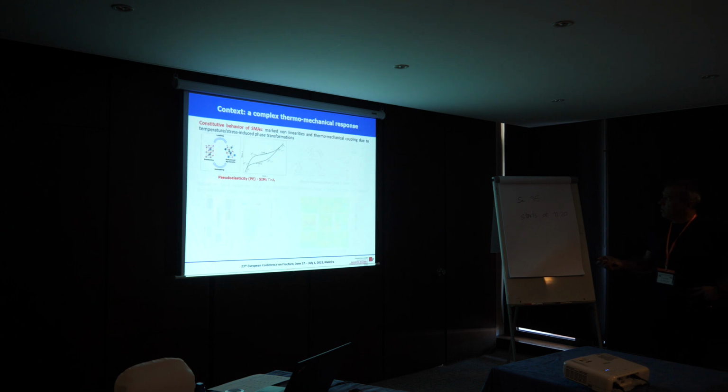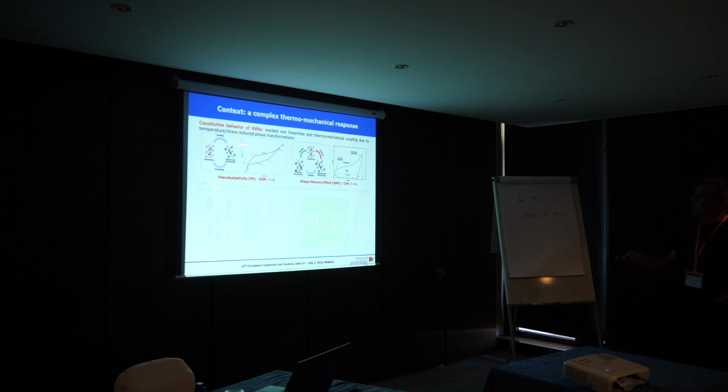Thanks to this feature, the material has very special properties, coupled with very complex constitutive behavior that is characterized by marked nonlinearities, hysteresis, and marked mechanical coupling. In particular, when the material is in its austenitic state, that is at high temperature, the material exhibits the so-called pseudoelasticity. It is a very large strain recovery capability. It is a kind of superelastic effect.